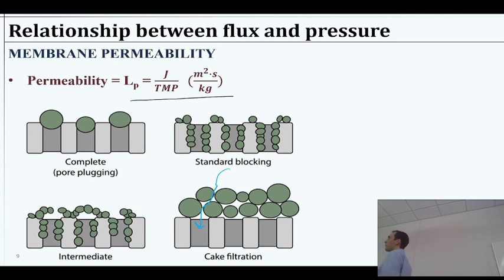If you try to push water through some sand, it should go pretty well, right? Try to push it through clay, not so much. So the permeability of clay is very low compared to the permeability of sand. It goes to show why in some places you can use septic tanks and in some places you cannot. Okay, so that's just one more term. You'll have that equation as well. It's not adding a whole lot, just another way to describe the porosity of a system. Porosity is its own term, and we'll not go into that.